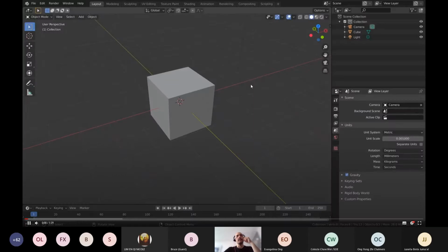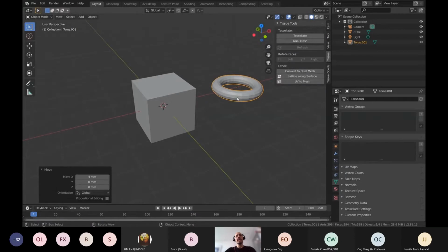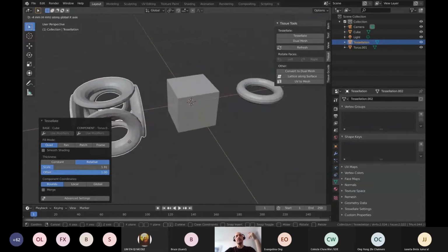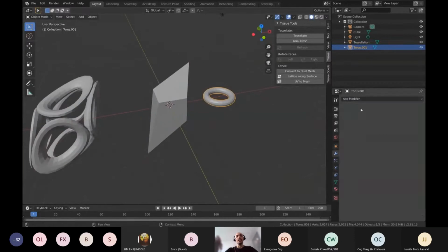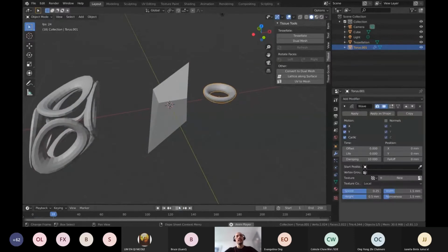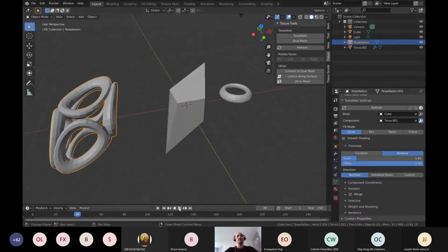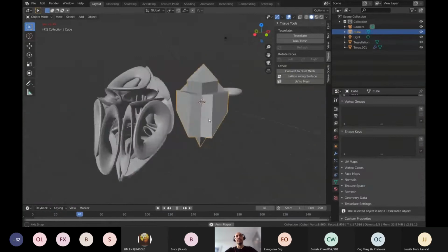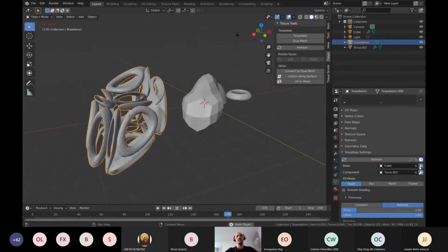In this small and simple animation, you can see how it works. This is the interface of Blender. You create just two objects. The base object is the cube, and the torus, the donut shape that you see, is the component. With the add-on, you can easily select one geometry and apply it to all the faces of the other geometry. I think it's important to keep the workflow non-destructive, so you always have the possibility to refresh the result according to the changes that happen in both geometries involved. If you change the base, you can easily refresh the tessellation according to the changes that you make.